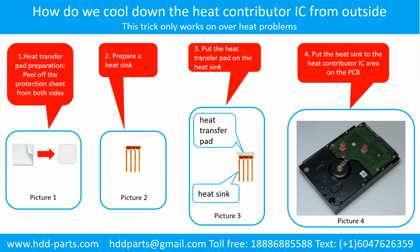Step 1. Heat transfer pad preparation. Peel off the protection sheet from both sides of the heat transfer pad, like picture 1 shows. Step 2. Prepare a heat sink, like picture 2 shows. Step 3. Put the heat transfer pad onto the heat sink, like picture 3 shows. Step 4. Put the heat sink to the heat contributor IC area on the PCB, like picture 4 shows.